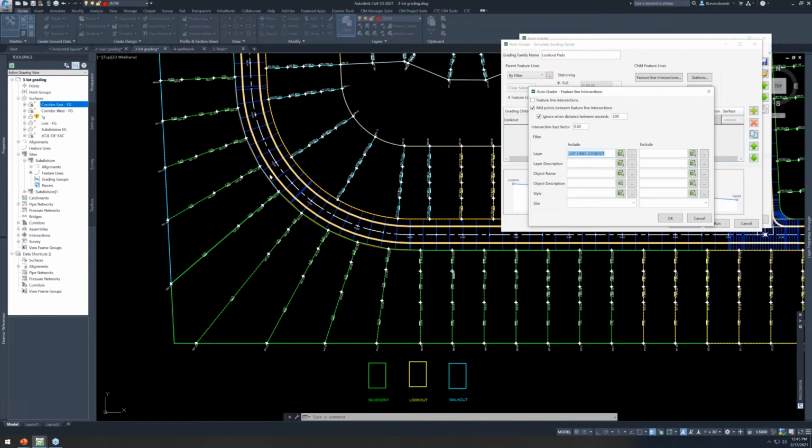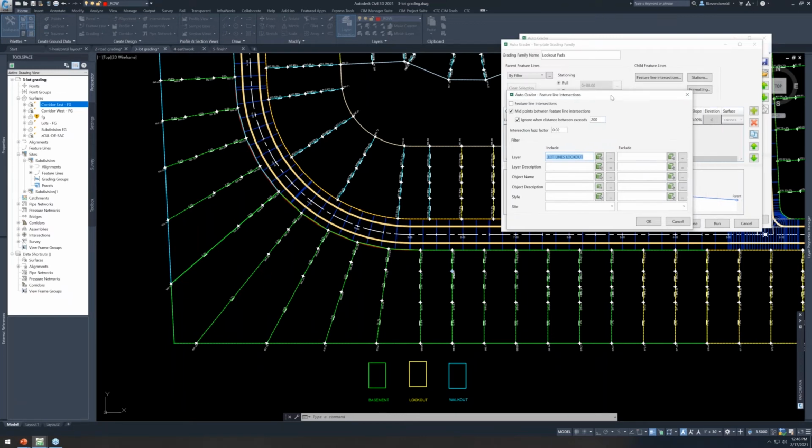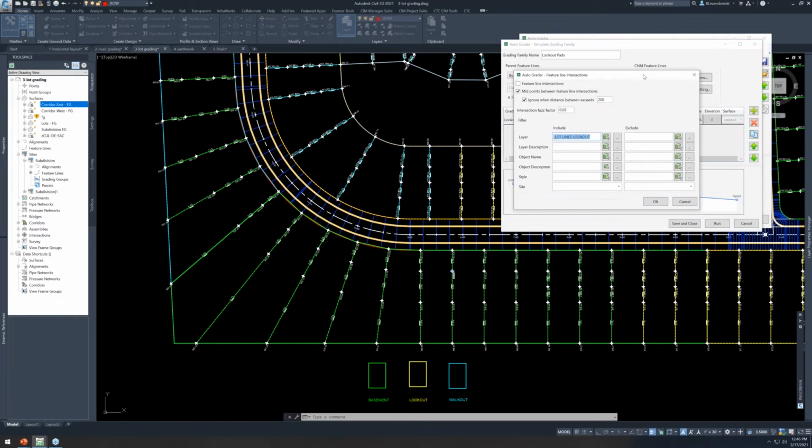We're going to insert those pads based on right-of-way so we get the proper orientation and it gets centered in the lots. And then using some analysis tool or just simply looking at our labels, we're able to see, do I have that minimum drainage away from the house? I've got a few ideas on a few other features I want to add into AutoGrader that'll kind of automate some more of that. But for right now, we're going to insert from right-of-way.